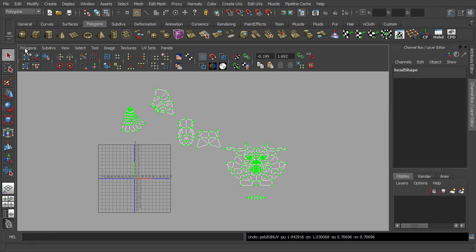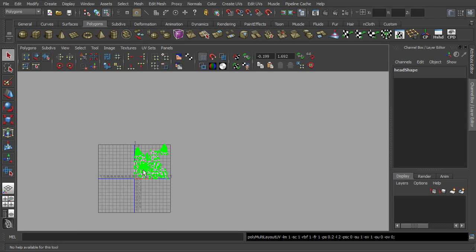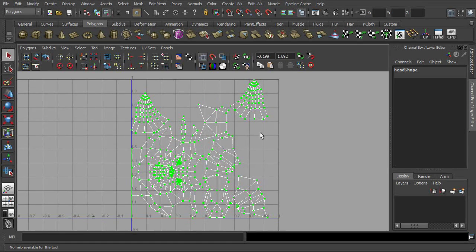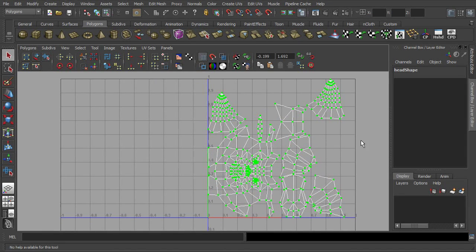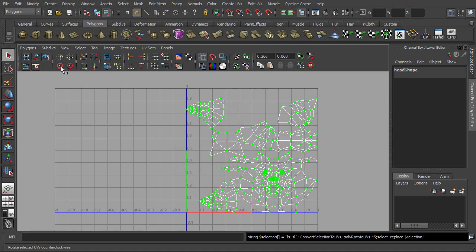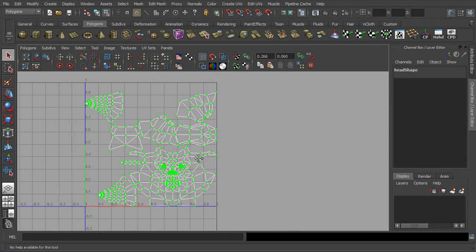These would automatically help you to generate a layout. However, most of the time, this automated approach would not be able to deliver an optimal layout, which matches certain mip-mapping and LOD requirements, and it would not help to maximize any given resolution. By far, manual operation is the best workaround at the moment. You will need to overlay some of your UVs to retain the maximum pixel resolution.